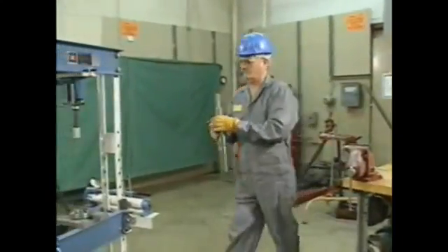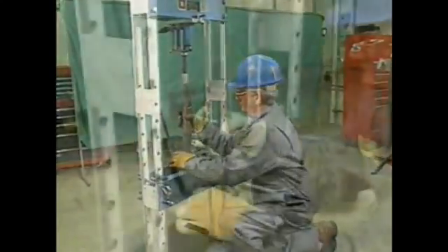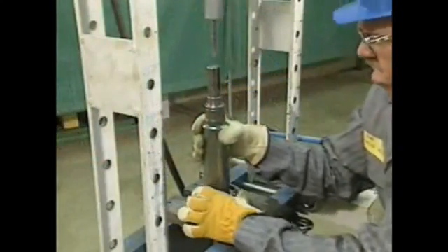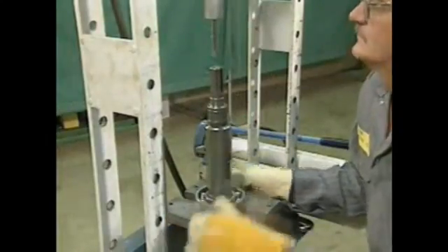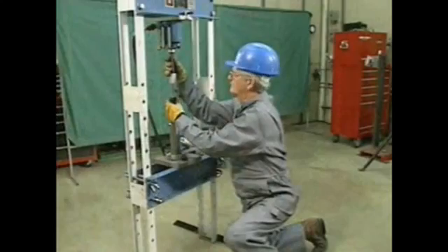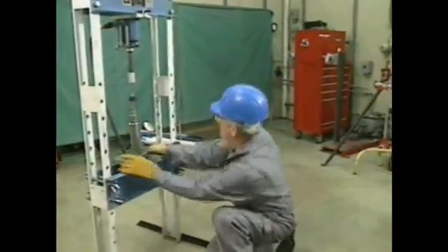Bearings are precision parts, and they must be installed as precisely as possible. How the bearing fits onto a shaft and the kind of mounting that is used are both important to the proper functioning of a bearing. The term fit refers to the tightness or looseness with which a bearing is installed onto a shaft.